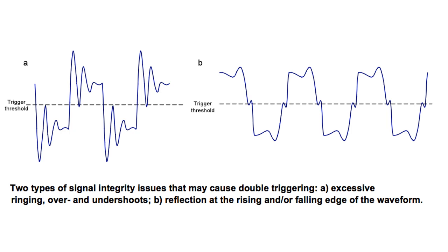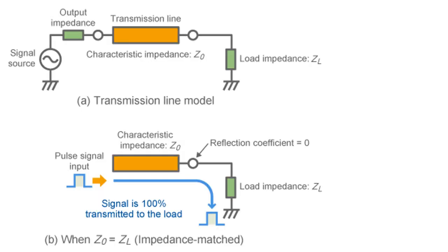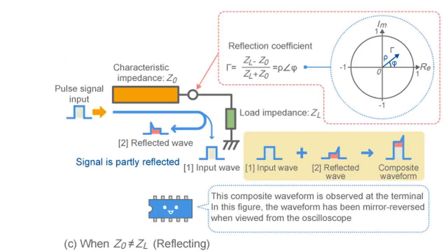During travel on the line, if the signal encounters changes or non-uniformity in the impedance of the line, it will suffer reflections which cause ringing and signal distortion. Moreover, the faster the signal rise time, the greater the signal distortion caused by changes in uncontrolled line impedances. As we mentioned earlier, if the signal encounters a discontinuity in impedance during its travel, it will suffer reflections which cause ringing and signal distortion.